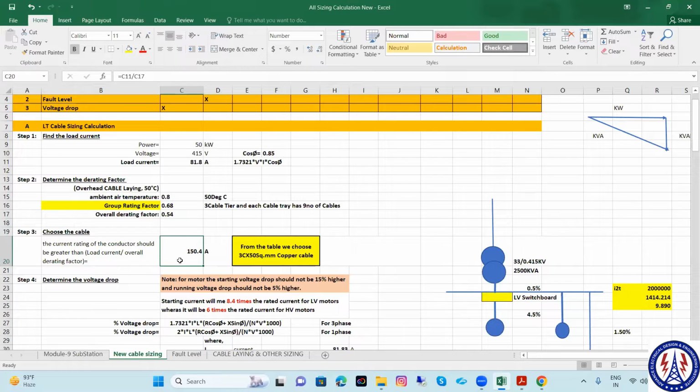See, the fourth core is used as a ground. The fourth core will be the ground in that case. That is not the phase, that is not the neutral conductor. Maybe you are right that harmonics might be there, but in the motor it is not possible to have neutral. So that will be the earthing core only, because it is not possible to ground that dewatering pump.